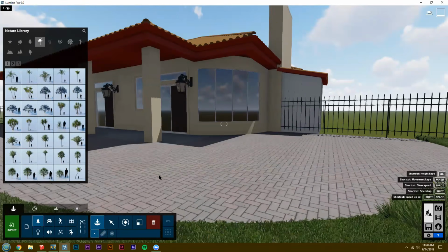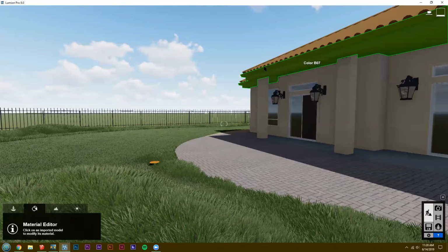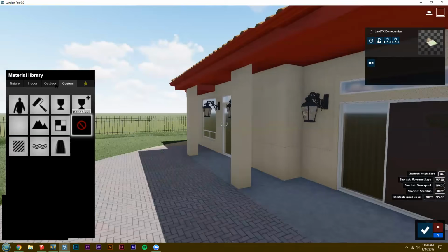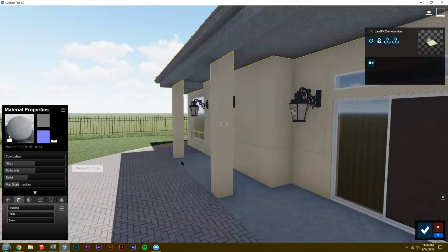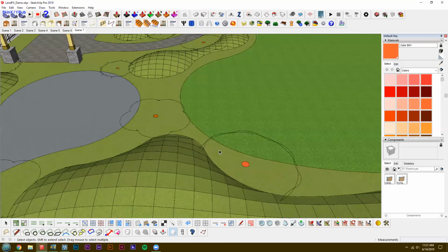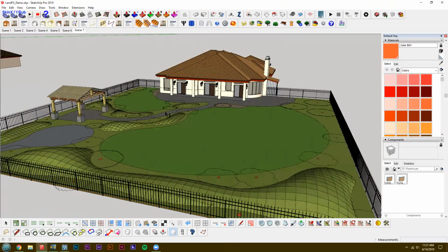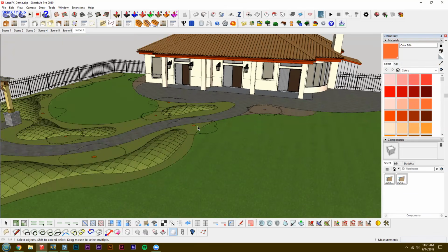I would assume that you should use caution as well, bringing in 3D warehouse models of stuff, from face creation to insertion points to scale and stuff like that all matters, right? Yeah. So I'll always bring in something from the warehouse in its own file. I'll never bring it into a finished SketchUp model, just because I don't know necessarily how large that file is.